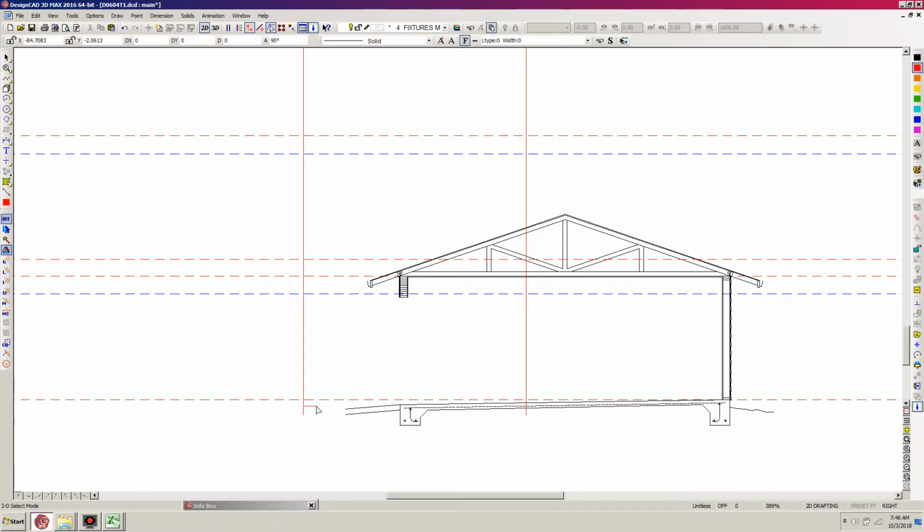Hit enter. So now the quick and easy way to deal with this is just to right click, and it clicked on and selected the line. I'm going to hit enter and it'll select the tread. I'm going to hit N and just duplicate this, each one of these, and right click to the previous one. March on up here, and we'll make sure that this ends up landing right at the finished floor height. And it looks like it does.